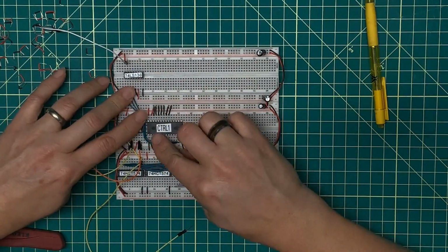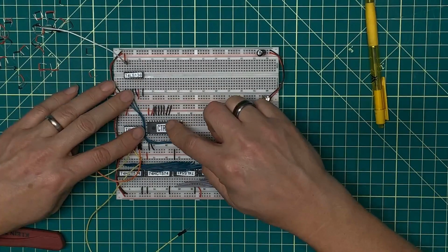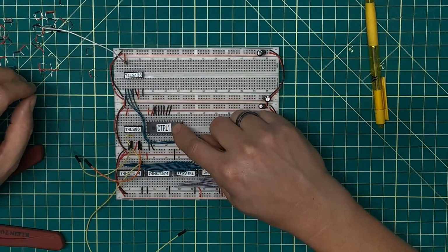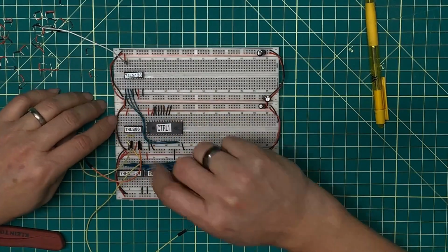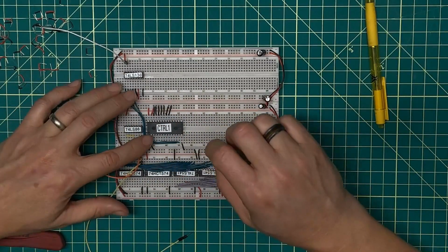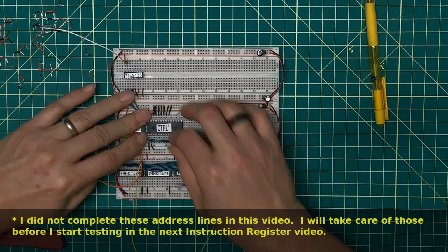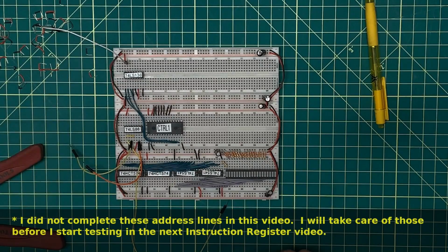Okay, so I pulled these down this direction simply because I'm going to need to be able to take this EEPROM in and out regularly to reprogram it for a while. I do want to be able to get to it without having all the wires going over the top of it, at least not yet. And so that will leave then the 8 address lines that I will want to pull right here. We'll get to those in a second.